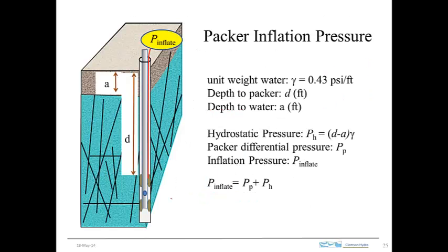Okay, so one thing that is important to recognize is that when you inflate packers, you have to use the correct pressure. Packers expand when they're pressurized, and the pressure that a packer feels is really the difference between the pressure that inflates it and the pressure that contains it on the outside.